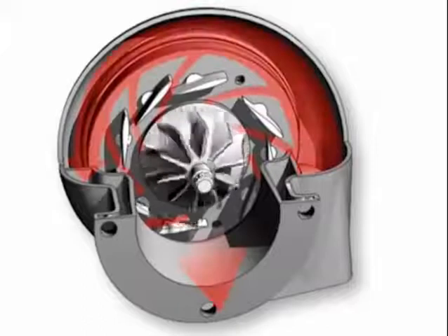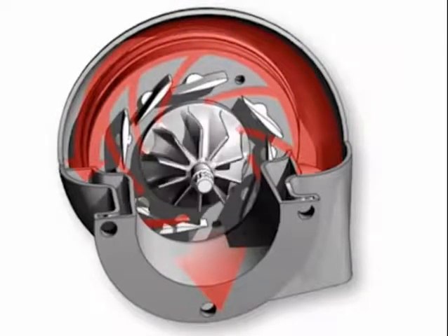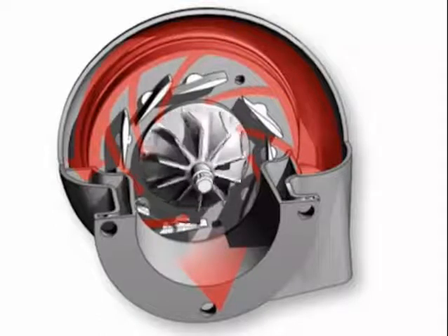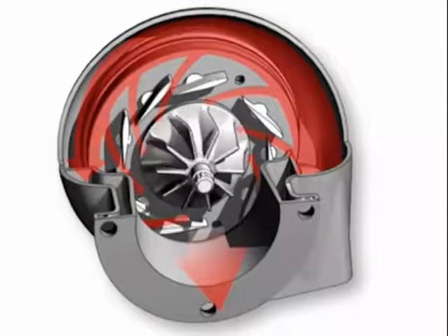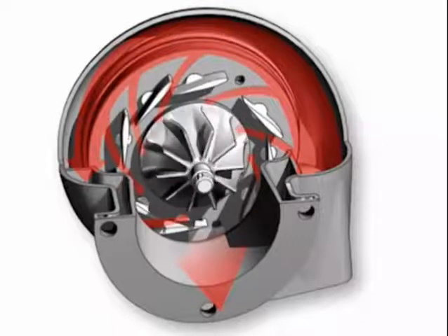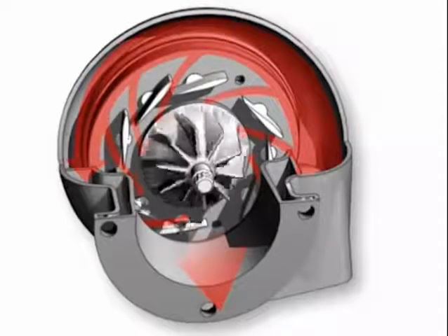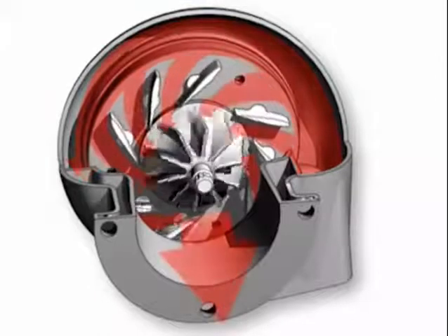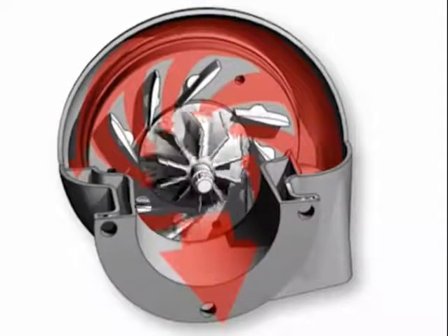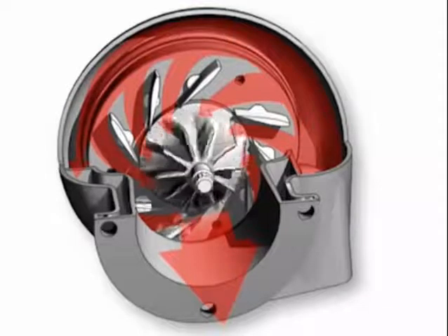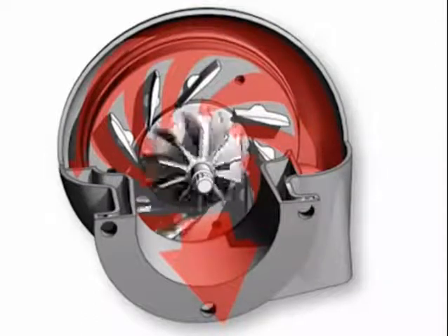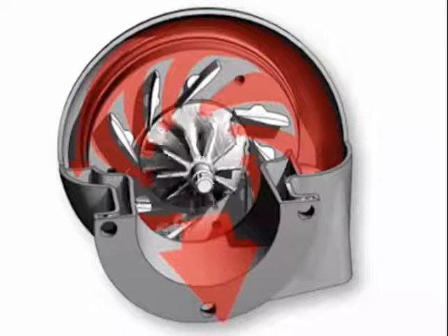By closing the guide vanes, the VTG simulates a small turbine able to achieve higher rotational speeds even with lower exhaust gas availability. With increasing exhaust gas availability and reaching of the speed of rotation for the maximum charge pressure, the guide vanes are opened. The turbine increases in size, through to full output, at which time the guide vanes are fully open.